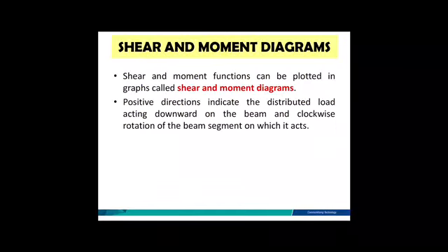How to analyze the beam? How to precisely analyze the beam? You need the shear and moment diagram. Shear and moment functions can be plotted in a graph called the shear and moment diagram. In this chapter, the sign convention is the same as in chapter 1, which means you need to follow the given sign convention. For example, I'll show you.